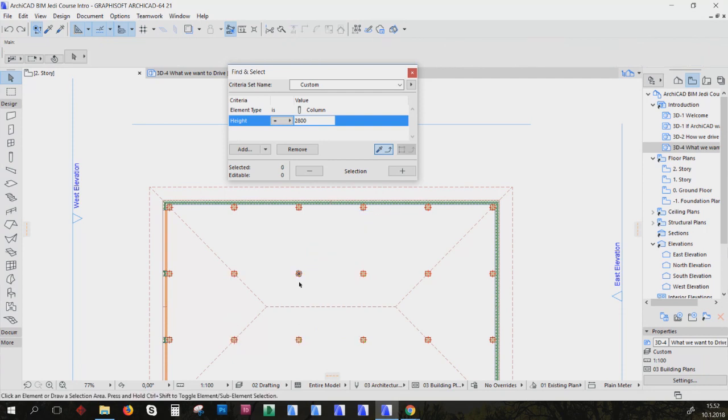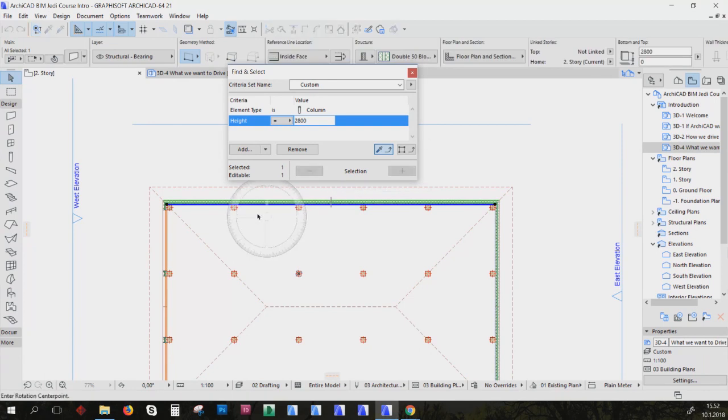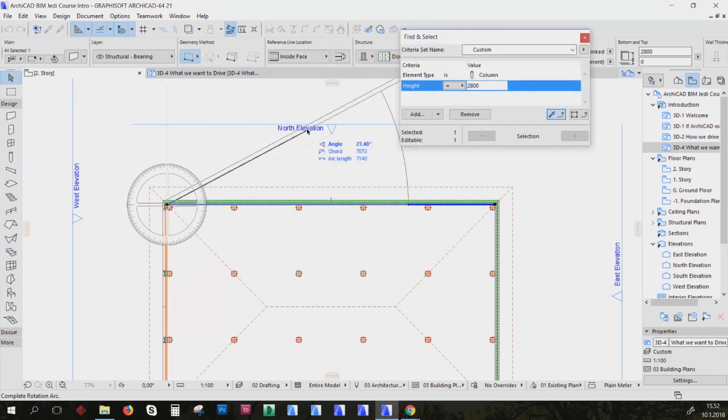So to rotate, we've got Control E. Grab a wall and we want to rotate it. So we just Control E, start at the start, and then around there. Are you all aware that the Shift key locks you into set angles? I know I've seen some that didn't even realise. You want to come around to 90 degrees, you can quickly just Shift, and it will lock you to the nearest point. 30 degrees, 45, 22.5, and you can actually customise those as well. But I won't show you that for now. We'll do that later.